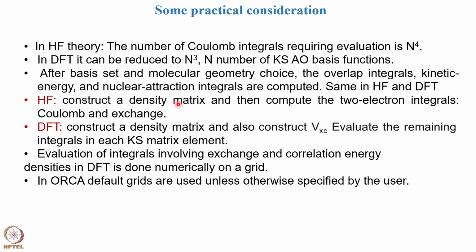Change in the grid size can lead to some changes in the total energy, which is fine, perfect, but the energy differences, the bond and the geometry may not have to be the same. If it is not converged with respect to the grid size, then you have to change the grid size and check the convergence. In most cases, there is prior literature or the ORCA manual, where you can find out what the default grid size is for this kind of calculation.